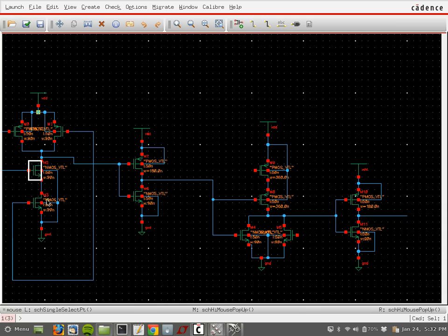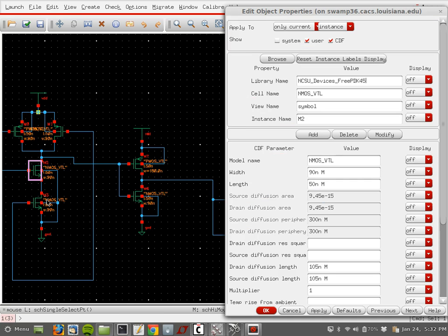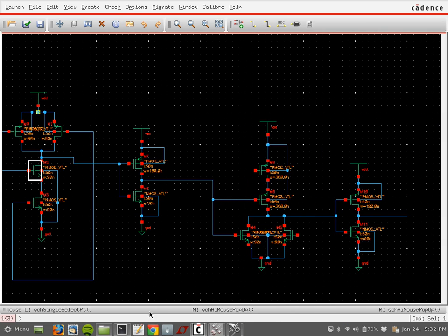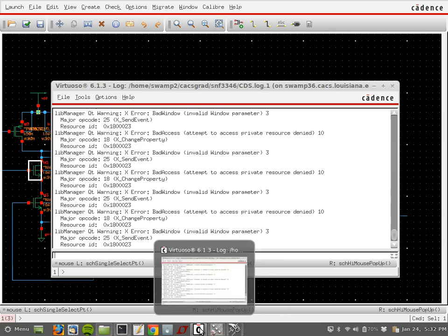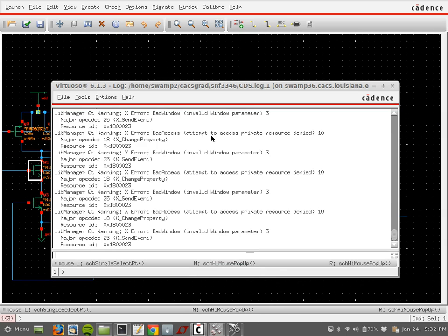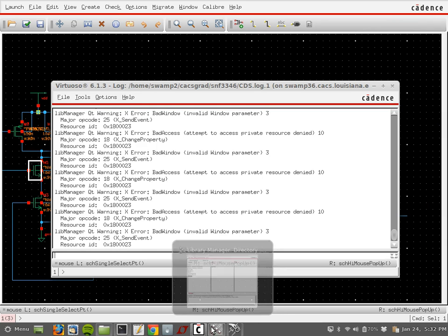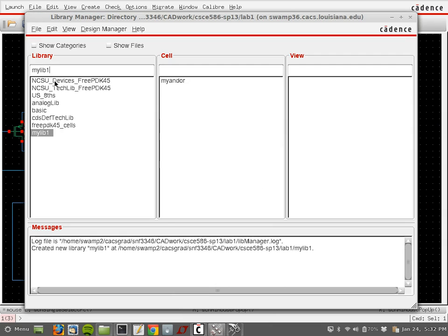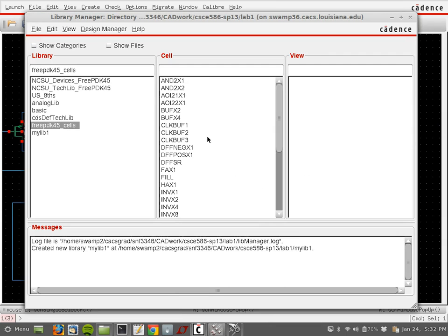Over here we have 2 NMOS in series. So I guess in this gate, we don't have to do it. We can make the transistor double the width, but it's not necessary. If you have doubts, by the way, you can look at their built-in libraries and see how they size their own gates. So let me look at their own AND gate and see what they actually did.